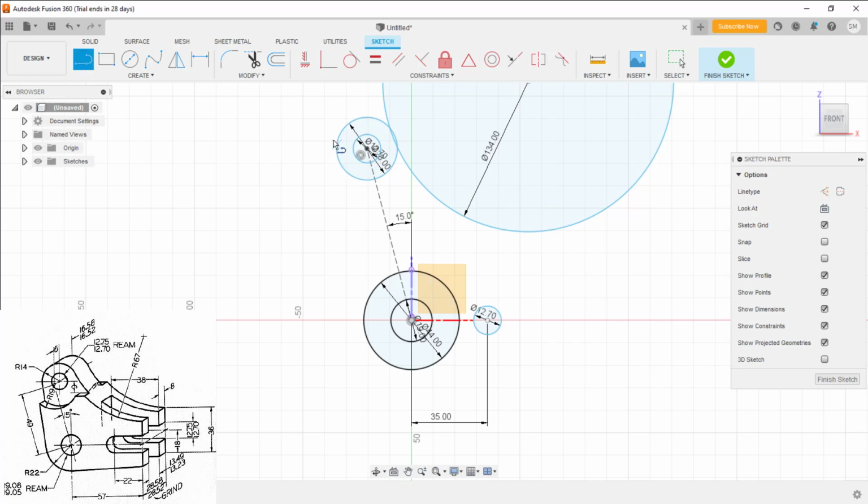Next thing, I need a line. Here, one side it will snap the tangency, the other side is quite difficult, so you need to manually define it between these two tangents. Again, for that too you can define the dimension. Yeah, this normal distance is given as 49, you can enter the same thing.